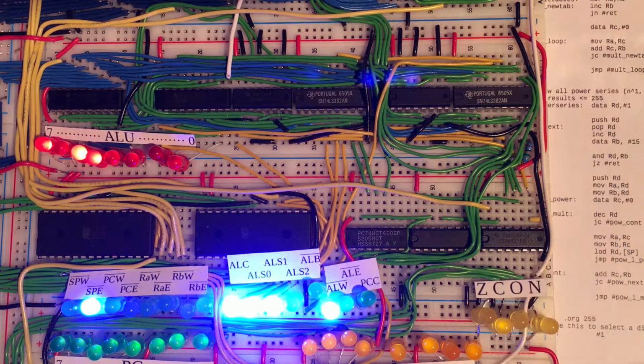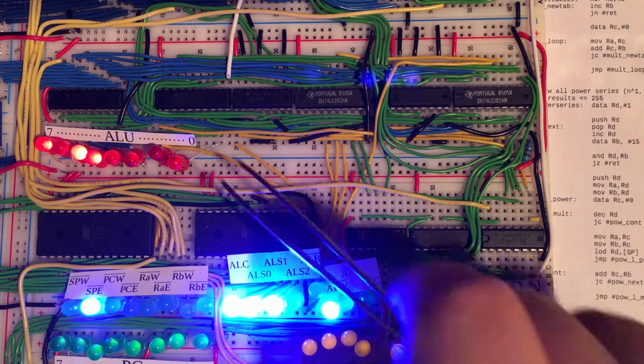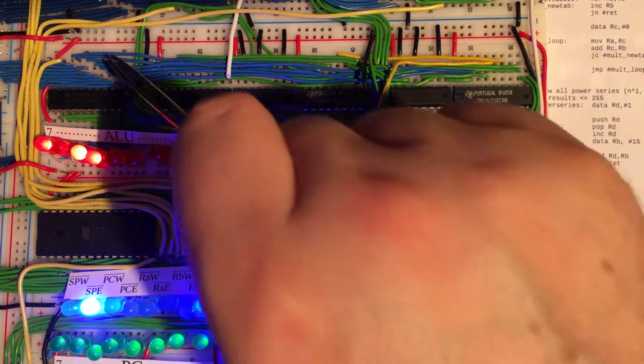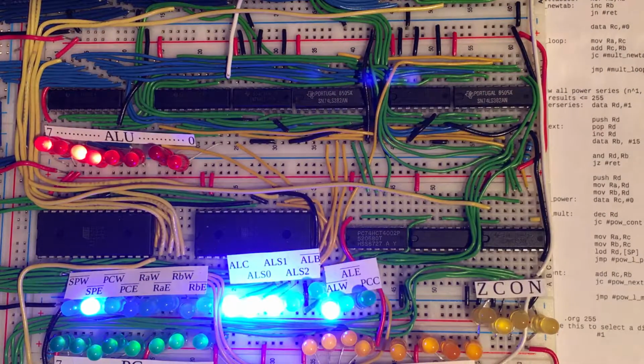And now in the case of the pop instruction, we simply want to increase the stack pointer by 1. We don't want to increase it by the value of the B register. So for this particular operation, that control signal is not being asserted. And so the first input into the ALU is coming from the bus, and in fact the bus right now contains the value of the stack pointer, because the stack pointer register is being told to enable its contents onto the bus.